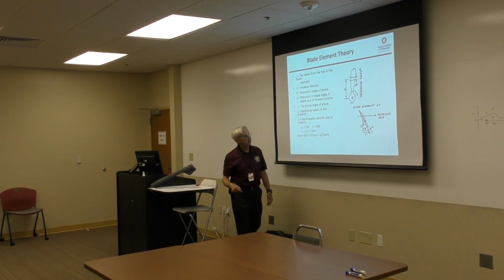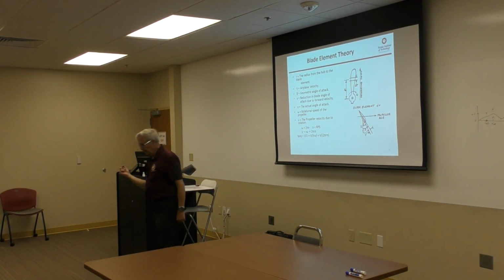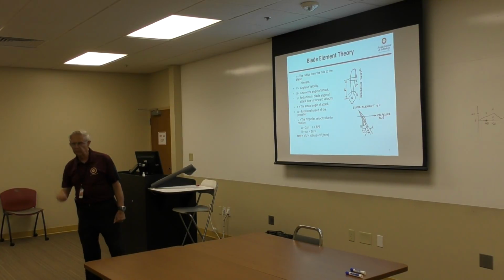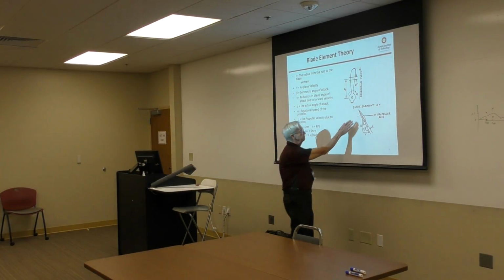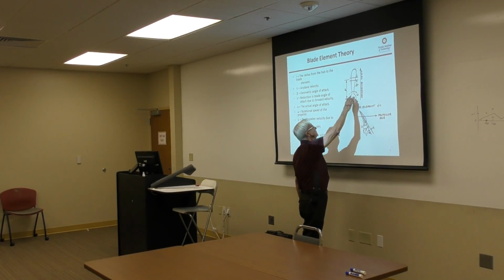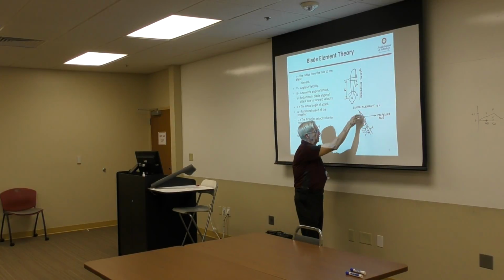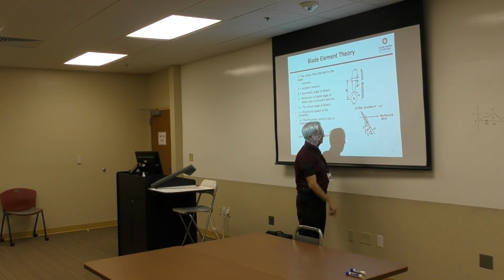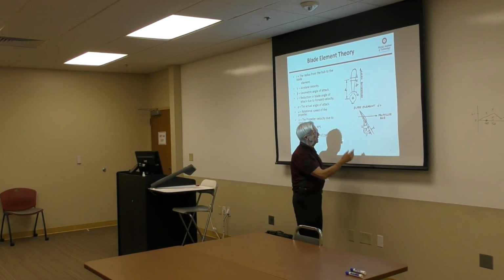You know, on the fact that it is rotating, so it has a rotational velocity, and then we have the aircraft's velocity through the air. And so when we do that, if we take some blade element here, we'll say this is it, some radius out on the propeller, and we look at it, we can see that here's the airplane velocity, or the forward velocity that it's making.